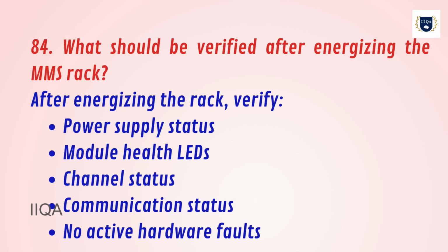84. What should be verified after energizing the MMS rack? After energizing the rack, verify power supply status, module health LEDs, channel status, communication status, no active hardware faults.